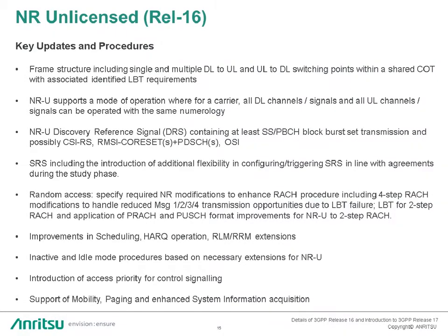Some more details on NR unlicensed for Release 16. So there is improvement in the frame structure switching points, where it's possible to switch between downlink to uplink and uplink to downlink single or multiple times.